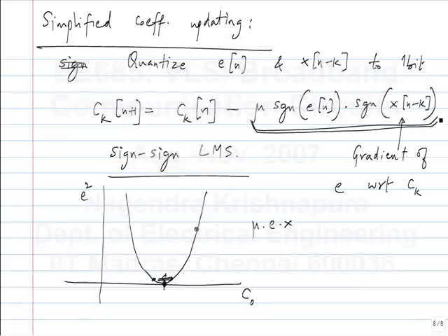Yeah, that's possible. So this is also done sometimes, that you adapt for some time. Maybe it can be related to the magnitude of V, or maybe you wait for a certain amount of time. That is, you know that it's going to take this much time to adapt, you leave maybe 5 times that time and then stop the adaptation engine. In that case, the coefficients will be steady, so the adaptation noise will be 0.